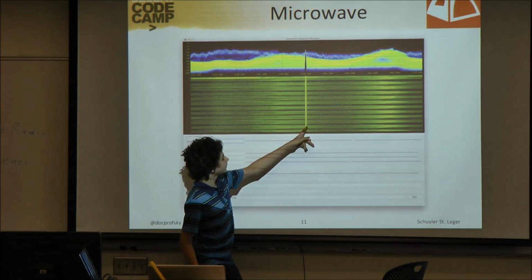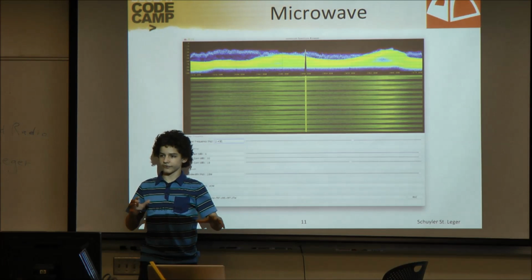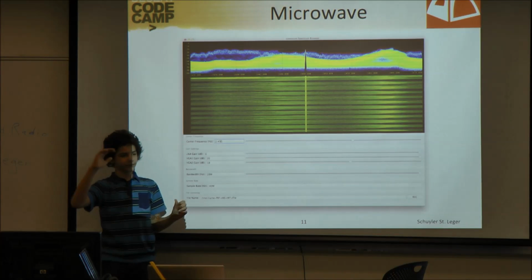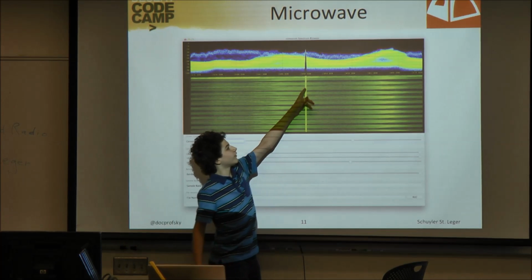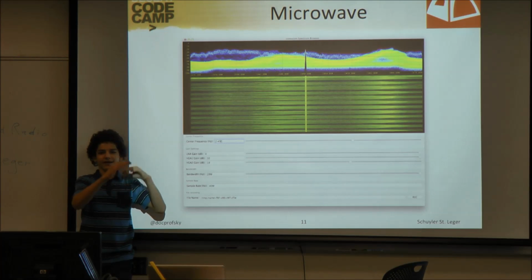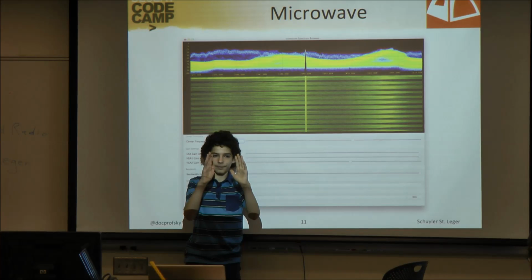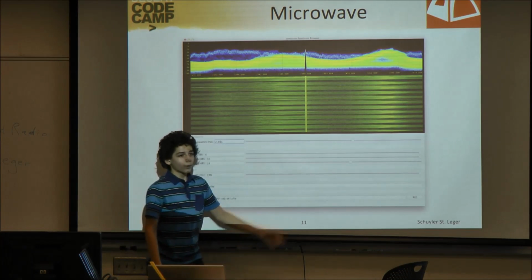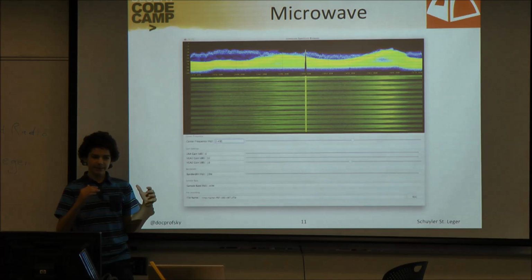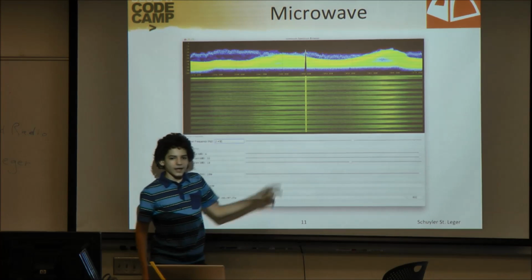One other thing you'll notice here is there's this constant peak. This peak isn't actually in the spectrum. This peak is what's called a DC offset, and it has to do with the way you sample the data. When you shift the frequency down from, in this case, 2.45 gigahertz to essentially 0 hertz, you're going to get some DC offset, so you'll get this peak in the middle. You can get past this by, if you have a narrower band signal you're looking at, tuning off to the side, or you can just ignore it. There are some things you can do in the radio's hardware configuration to actually get that peak to go away, but unless you need the entire bandwidth and this peak is going to horribly mess things up, it's probably okay.